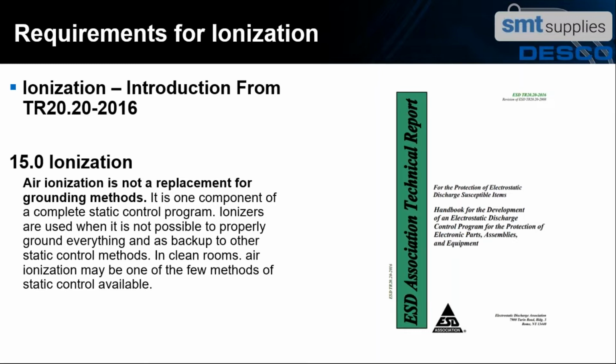knowledge base there. So, ionizers are not a replacement for grounding. It's just one component of a static control program. And ionizers are used both in companies that are handling static sensitive devices and also in companies that use it for particulate control in clean rooms, sort of two separate applications.